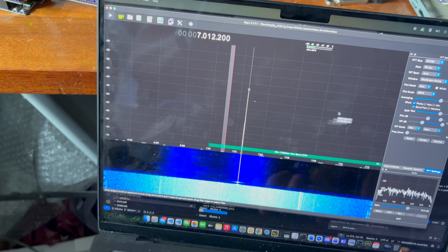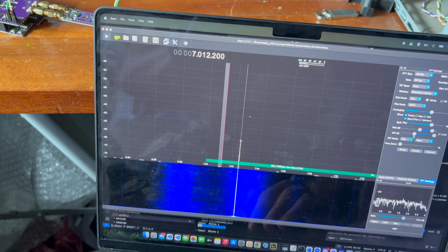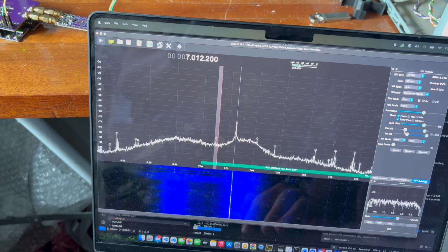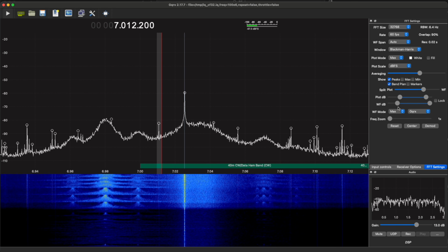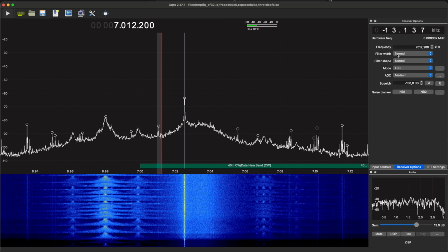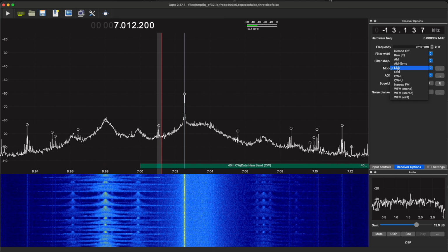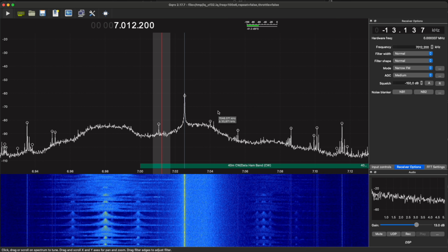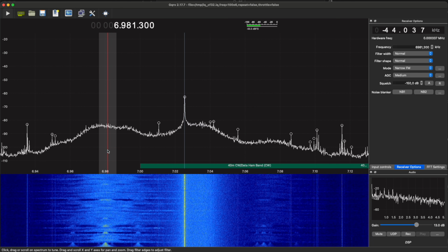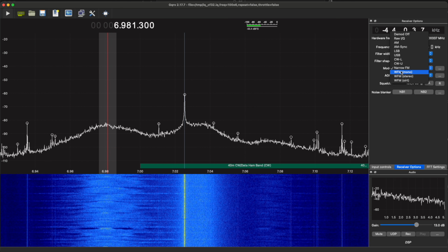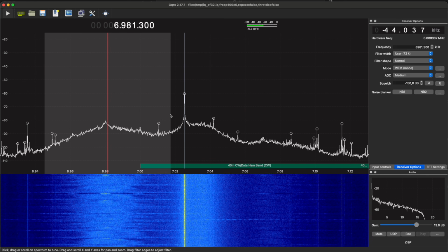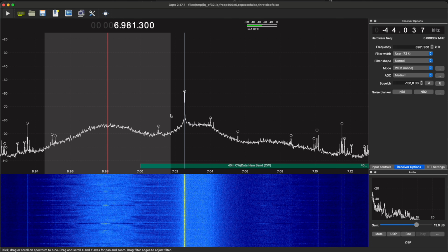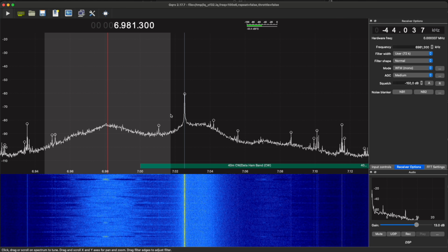Notice that I can't be bothered to change the LO frequency in GQRX. Obviously, we're not listening to FM broadcasts at 7 MHz. The antenna is still the same 40-meter wire in my attic, so it's not exactly tuned for the FM band, but of course the signals are powerful enough to make it past the mixer with just the right filter, even though they're not as strong as what's coming through around 7 MHz. Let's try changing the modulation to wideband FM and see what we get.